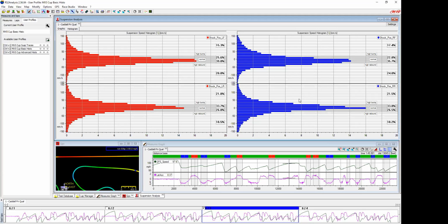And again, that's why it's so important for you to mount the potentiometer either even Steven with the shock, so it's 1-to-1, or do that motion ratio, so then you really know where this is actually hitting. If I were to have not applied that motion ratio correctly, I would be getting some false transition numbers, and I would be adjusting the high speed when the low speed probably is what I was shooting for. That's why we do that.